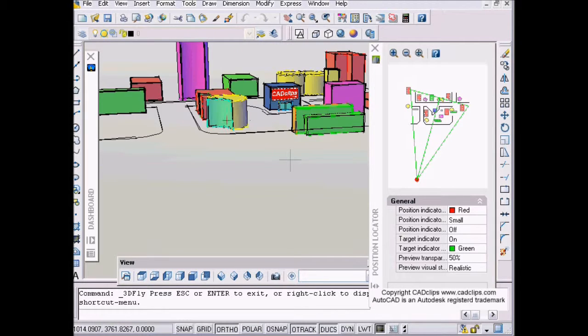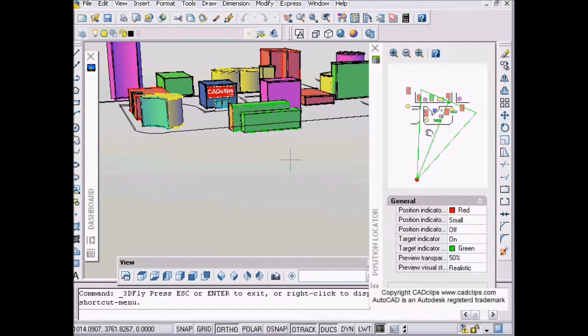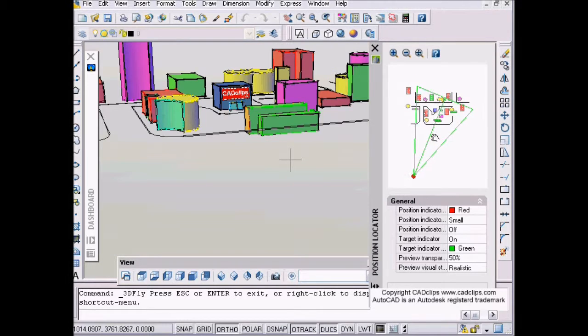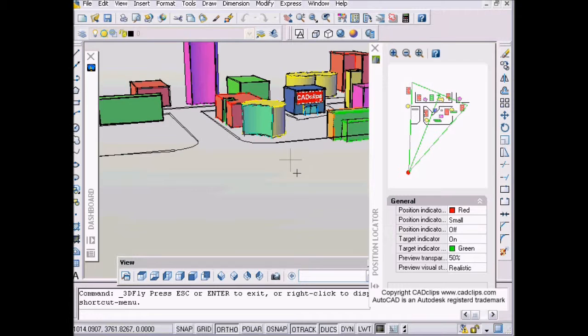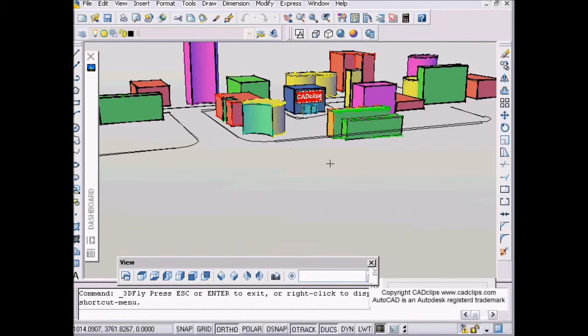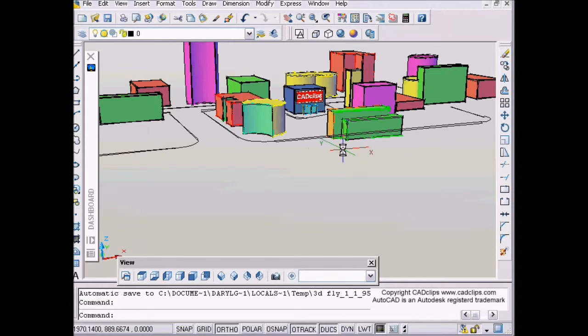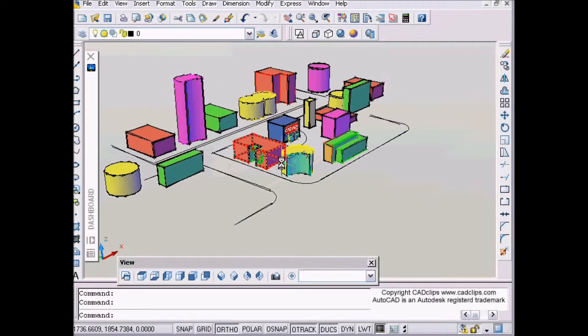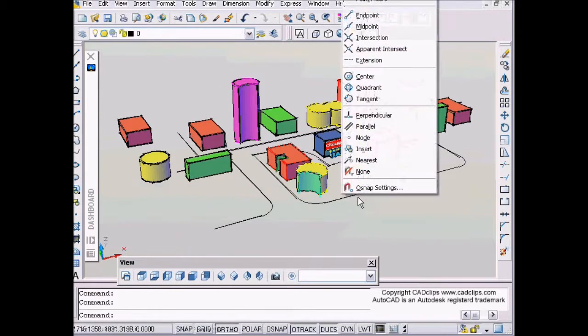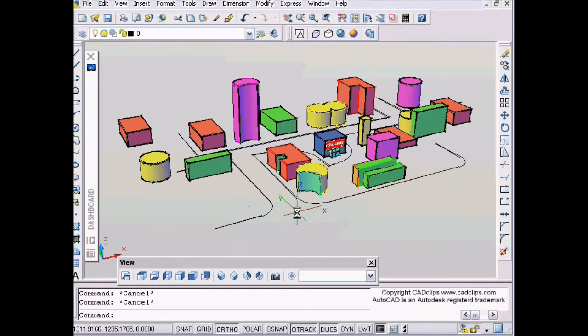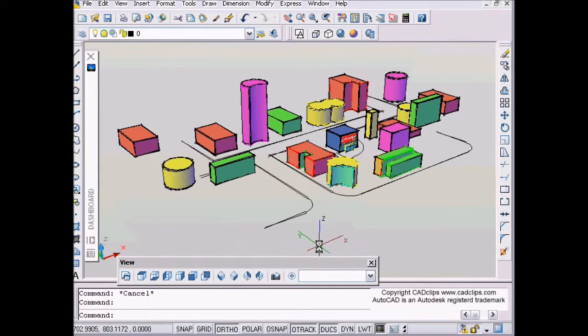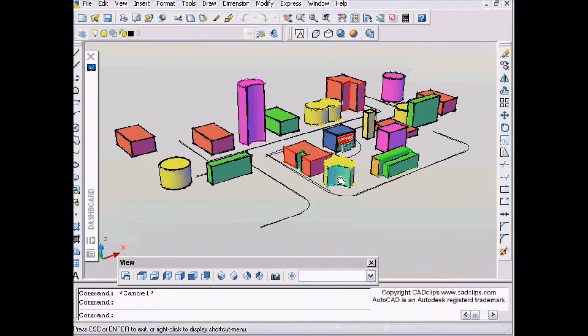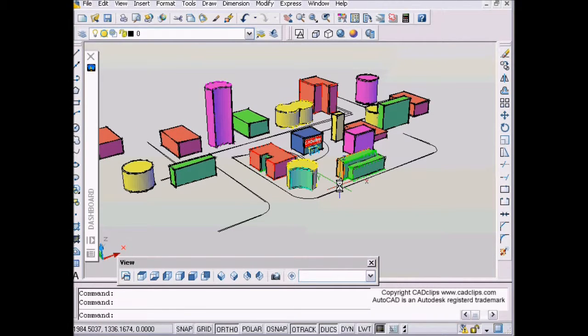Okay, and then remember again, using a mouse button over here. Again, you can take that and just move that if you want right on screen. Okay, and then sometimes if things get all botched up, you just hit enter and it bumps you out and it leaves you in that view. Now I can use my normal pan command and my shift middle mouse button, maybe get myself in position, because it's going to take a bit of practice. Okay, and it really depends on the shape. The flyby is much better for the flying, for actually going through a path. To go through and turn around and come all the way back, I'm finding is a little bit tricky to do, but maybe over some practice I'll learn how to do that.